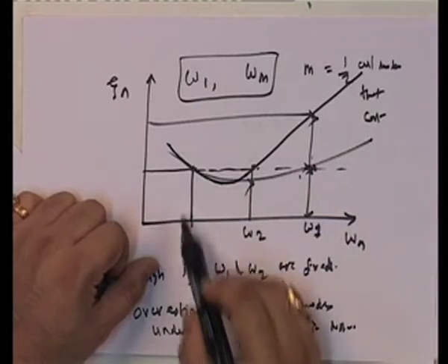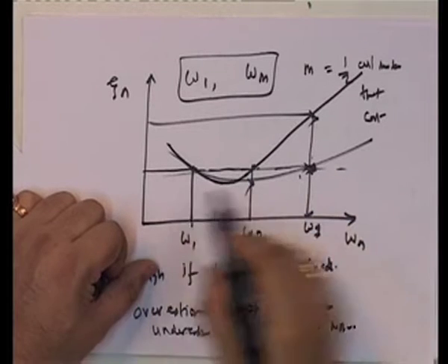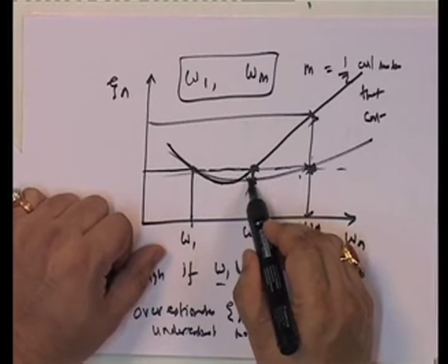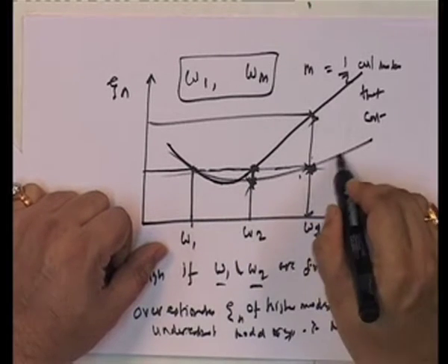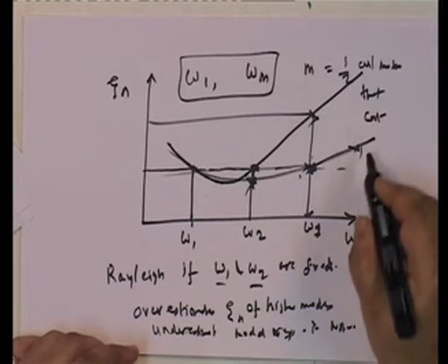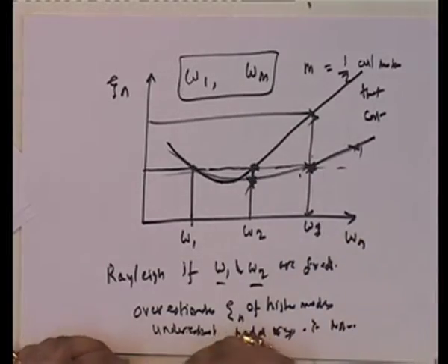Okay, if I take omega 3, omega 1 and omega 3 are at 5%. For omega 2 the damping is underestimated, so its contribution is overestimated. And then the higher modes, omega 4 and all, their damping is overestimated, and therefore you underestimate their response. But that's okay.